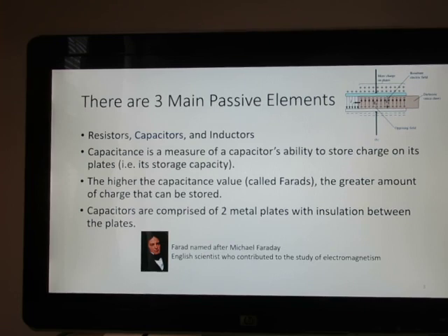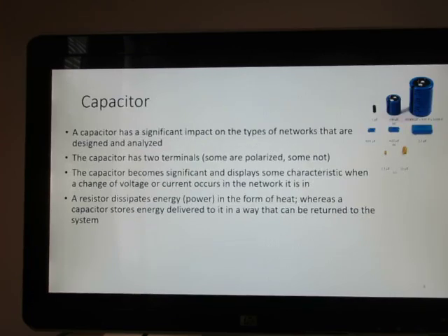A material called a dielectric is inserted between the plates, and that will control the amount of electric field buildup between the plates. On most printed circuit boards, you will notice a capacitor between power and ground on the integrated circuits. And why is this? This is to keep a smooth DC voltage by suppressing any voltage spike and minimizing the DC ripple.